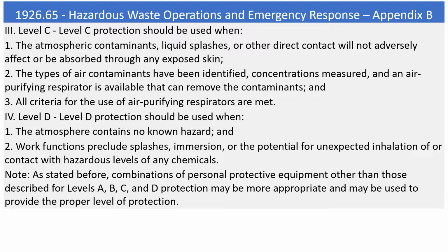3. Level C. Level C protection should be used when 1. The atmospheric contaminants, liquid splashes, or other direct contact will not adversely affect or be absorbed through any exposed skin. 2. The types of air contaminants have been identified, concentrations measured, and an air purifying respirator is available that can remove the contaminants. And 3. All criteria for the use of air purifying respirators are met.